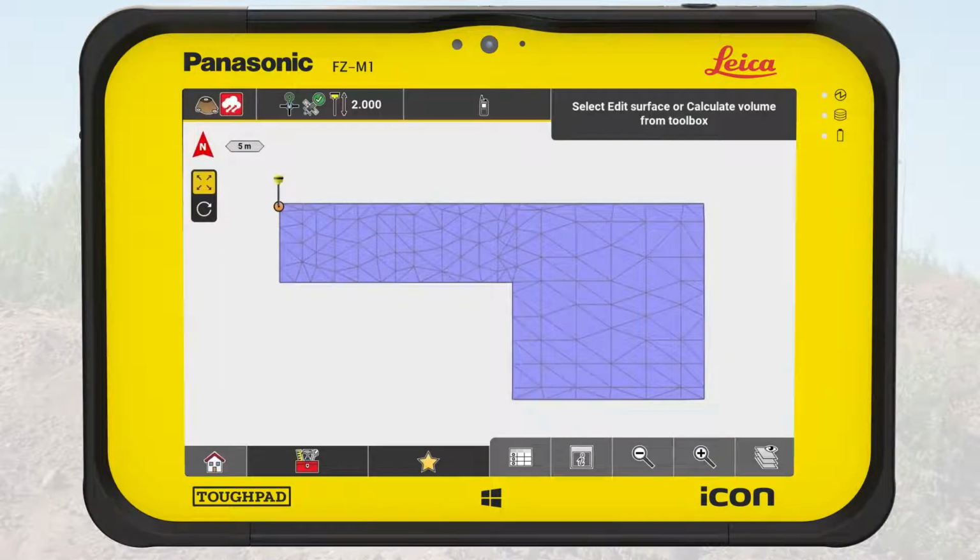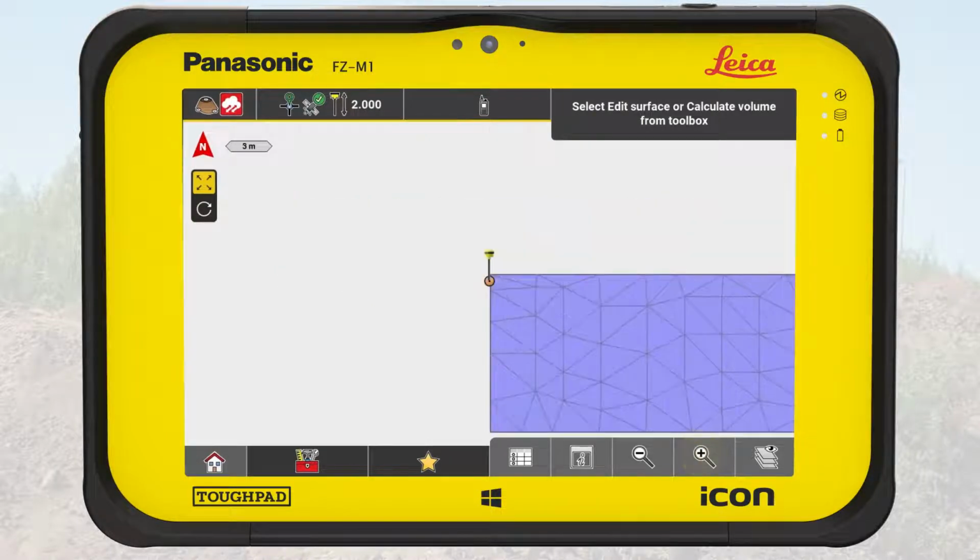The map shows the current state of the construction site. After the area was leveled out, a layer of gravel was built on it, including the curbs. A new surface was created and saved as subgrade.trm. The next step is to build a layer of gravel within the curbs.